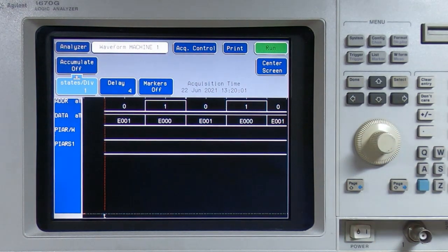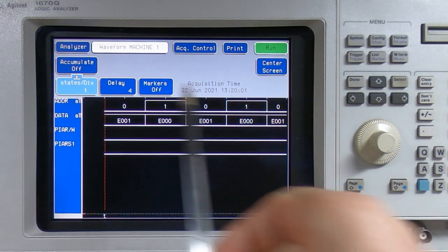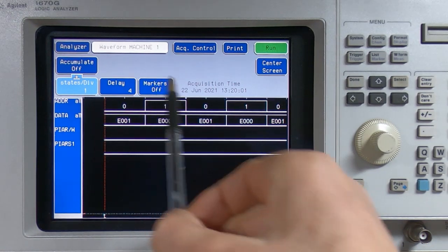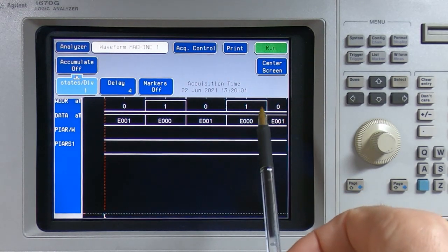Now, one thing I would point out is that because of the way this particular processor works, and in fact any processor that has multiple clocks for each instruction, you do need to be careful where you obtain the clock. So there are 4 clock transitions for each instruction in this processor, but that's not 4 transitions of this clock. This only has 1 cycle per instruction.